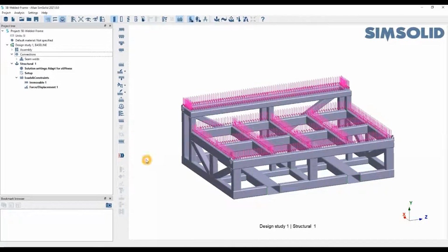Just so you know, you do have other loading options as well. We won't be touching upon it, but you can use enforced displacement. So if you're trying to replicate real test data and you don't have the forces behind it, you can use an enforced displacement to emulate that distance traveled. We can apply inertia loads, gravity loads, so any G loads that you want, any inertia relief. You can do remote loads, bearing loads, hydrostatic pressures, etc.